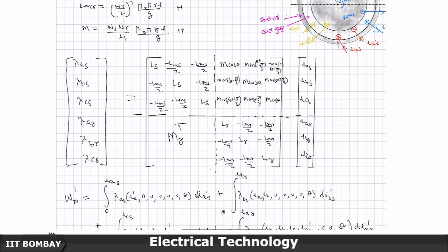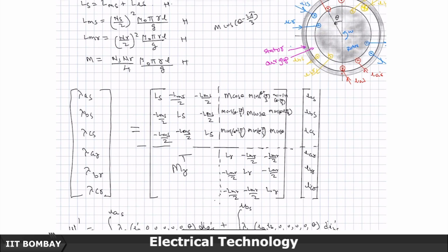So, this exact same structure is repeated here, but with the S subscript replaced by R subscript, which means the corresponding mutual inductances would be replaced like this. And now, the last thing I know is that for a linear circuit, when you write the mutual inductance in a matrix form, the matrix is going to be symmetric. Therefore, whatever is here, the transpose of this should come here, because when I take transpose of this whole matrix, it should turn out to be a symmetric matrix. So, this will become its own transpose, which is actually the same, because this whole diagonal matrix itself is symmetric.